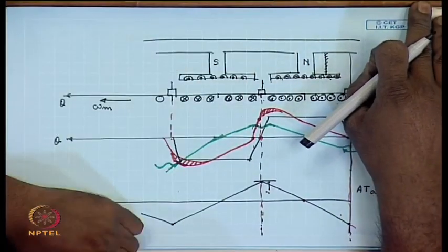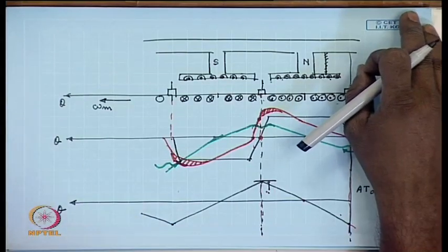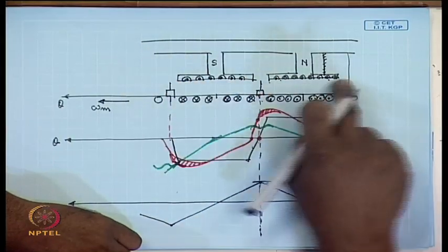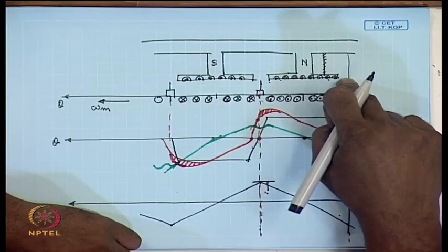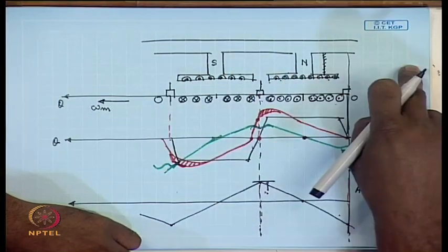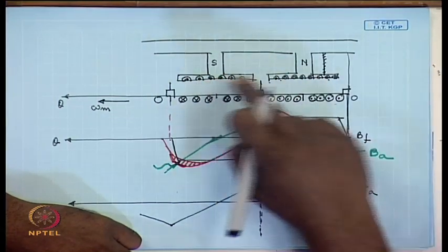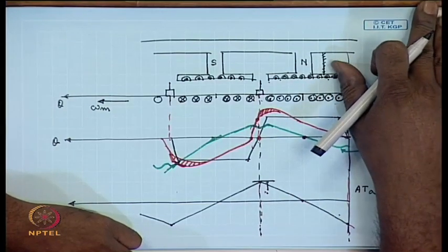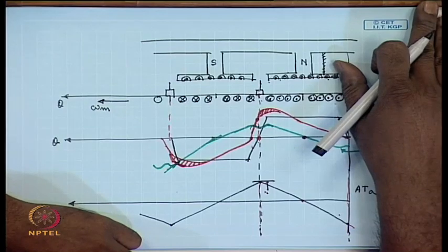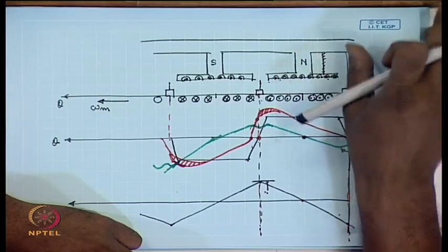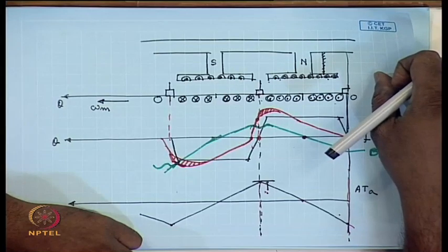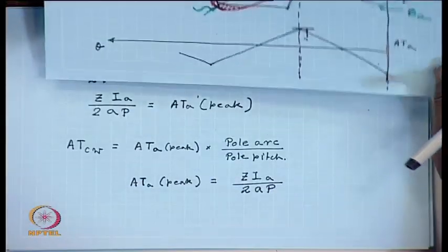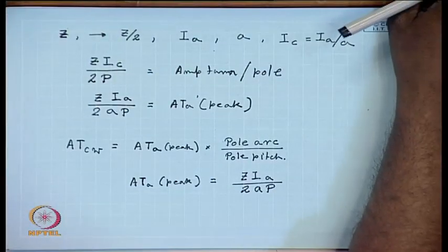will not be able to completely eliminate the armature reaction MMF, because the pole shoes do not extend over the entire armature surface. In fact, this compensating winding will mostly compensate for the demagnetization effect of the main flux, but it will not be able to compensate all the flux in the interpolar region.